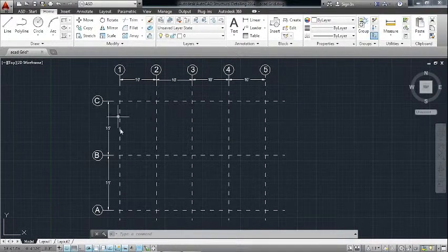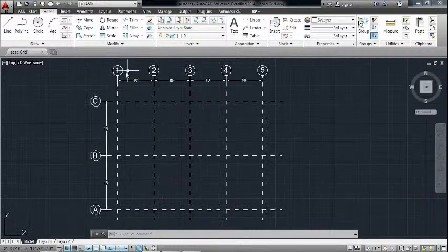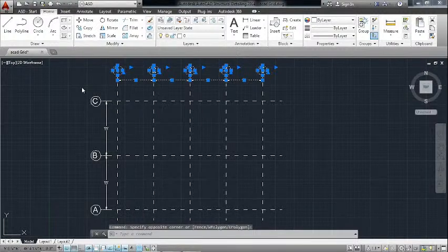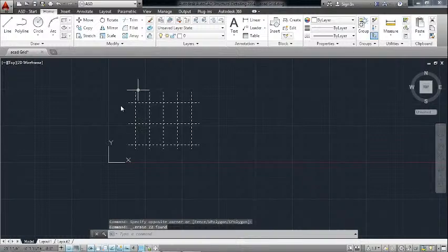In real architectural models, you will see the grid system and also the walls, bed system, maybe electrical wiring. So for the import to ETABS, you have to delete all the other items and leave only the grids. Here is the grid system. Before the import to ETABS, you should delete the rest of the items and leave only the grids. Here I will also delete these grid spacings. Now you can see only the grid system is here.